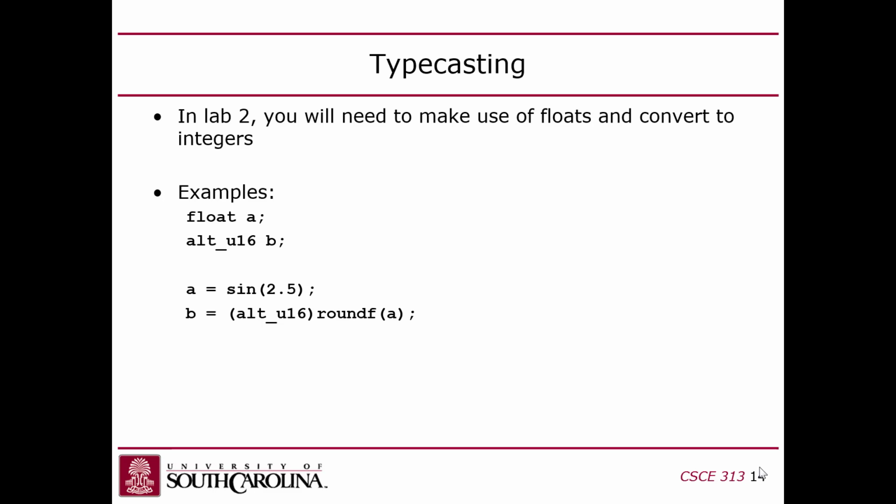The way it works is they wrote a loop in there, and I think they wrote it in assembly code because they wanted to know exactly how many instructions the loop body was. And from that, they knew how many clock cycles would go by in each loop iteration, right? And there's a constant in the BSP called cycles per second, right?